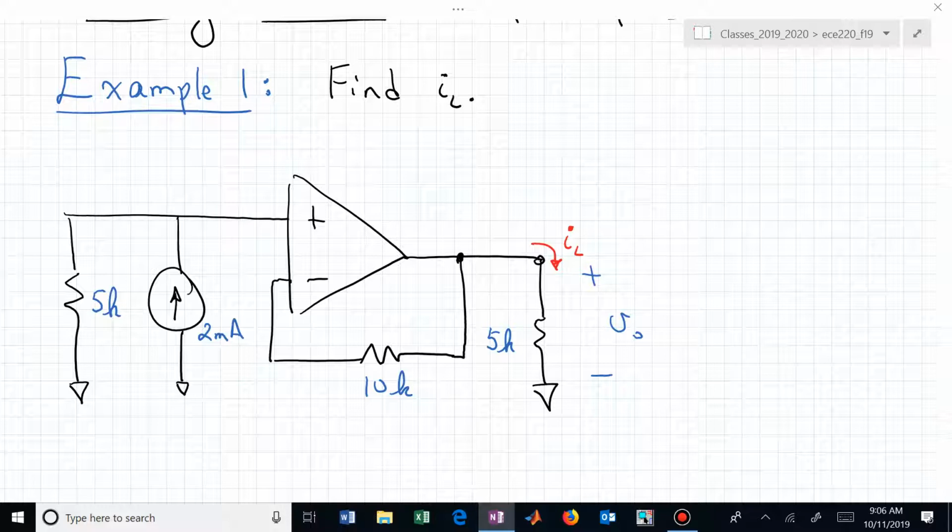But here is our circuit. Now, what's another key thing to keep in mind when you're solving these on the exam or in homework? Whether we're viewing this op amp as we've typically done it, or are we looking at it in a mirror? Has it been flipped? Have we inverted? Is it standing sort of on its head relative to how we've been seeing it? Here, now pay attention, the positive, the non-inverting input terminal is on the top. So if you're now looking for this feedback path, where do you want to find it?